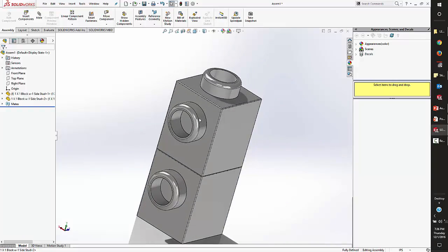It didn't take a long time, but one of the things you'll notice is I use the ability to guess what SolidWorks is going to do. If I pick 2 cylinders, SolidWorks is going to automatically try to make a cylindrical mate, and if I know it's going to do that, I can almost be ready with the Enter key. In fact, you can actually hit the right key immediately, and that's almost like the Enter key.